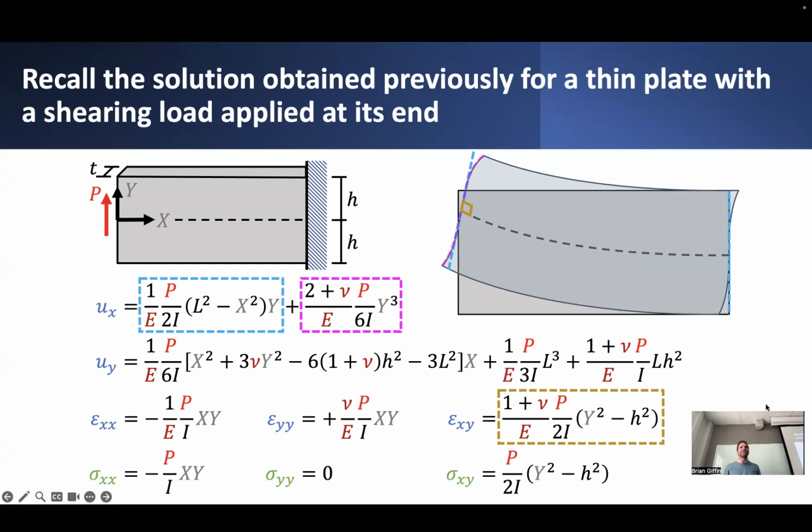And from that, we could also figure out the resulting strain fields, epsilon XX, epsilon YY, and epsilon XY shear strains, and how they varied as a function of position within this plate domain, as basically plane strains, assuming that the out-of-plane strains, the transverse shear strains or the normal strain normal to this plane, we said we don't really care so much about those details. We're just treating it as a plane strain problem and a corresponding plane stress situation.